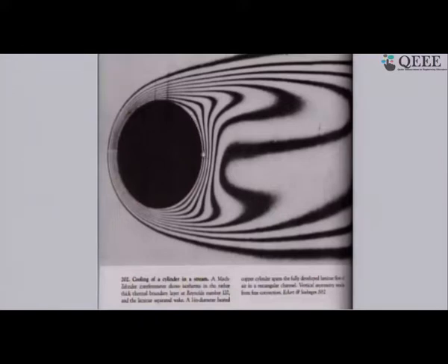Again, it recovers a little bit, and here the lines have come back a little closer, but not as close as they were in the front part of the cylinder. So you have a radial, azimuthal distribution of heat transfer coefficient over the cylinder, and this is determined by the flow that was taking place. In this case, as the flow was attached and it moved up to this point, this is what happened. This is the point where the separation was taking place. So the heat transfer coefficient is lowest because now the fluid flow is very small, sometimes in one direction, sometimes in the opposite direction. So that's the type of qualitative information we are able to get. And in this case, we could actually even measure the temperatures and get quantitative information about the heat transfer coefficient.